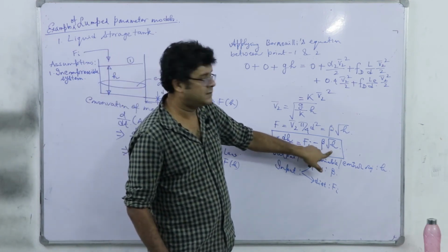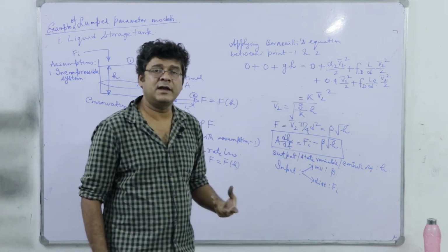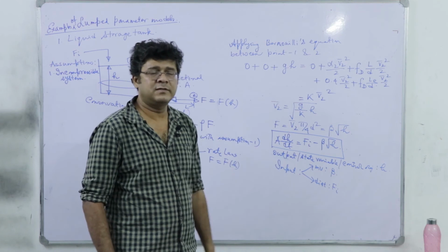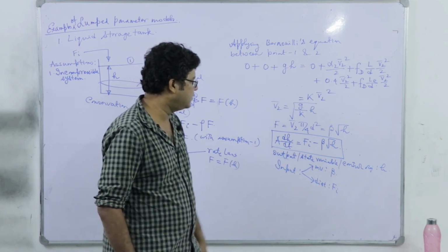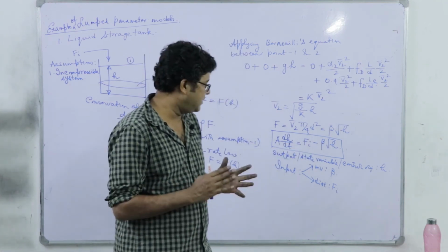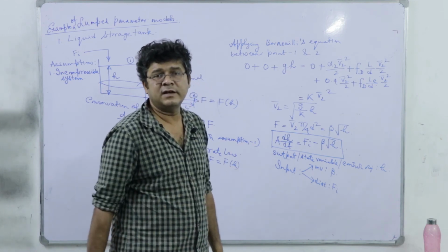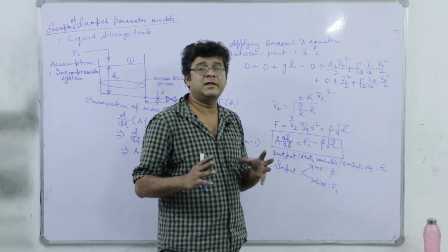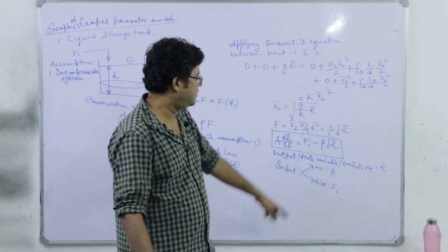Why? Because it is a nonlinear ODE. Nonlinear ODEs cannot be analytically solved. So we have a specific topic, which we will be discussing after one or two sessions, that is linearization. That's why we have to linearize. We have to linearize this beta into square root of H by using Taylor series expansion, and then it will be converted into a linear equation, but the accuracy of the mathematical model definitely will be compromised, right?